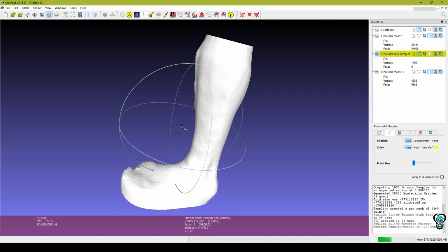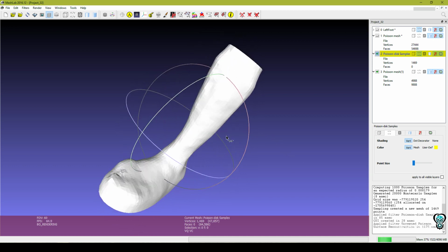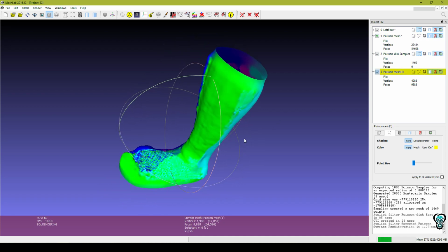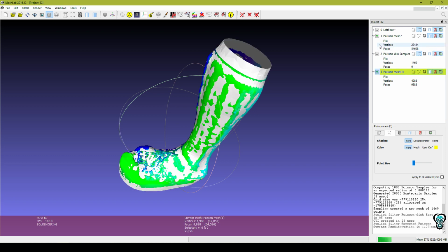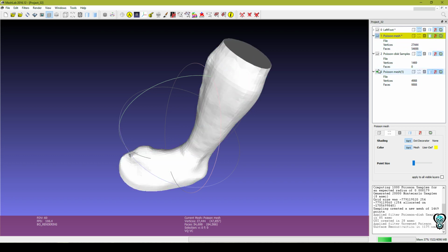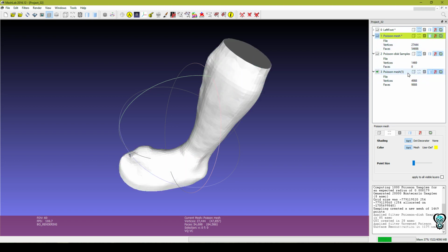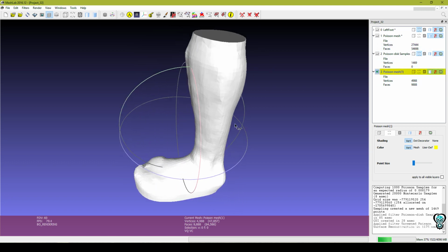And see, now you can tell that it's more of a refined mesh compared to this other mesh that seems like it has more faces. Of course, as you can see in here, there's just under 10,000 for the new mesh that I'm going to actually export, whereas the first one is almost 55,000 faces. So depending on how fast your computer is or how many faces you actually need, the other one would probably be unnecessary. Plus this one looks a little bit better.